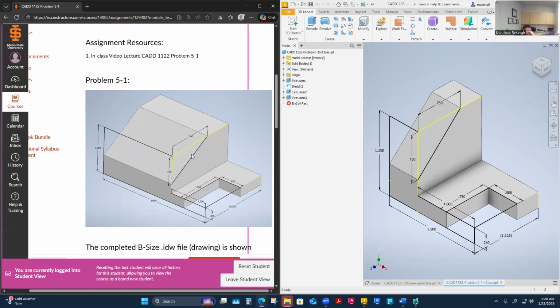7 core. So it looks like this bevel changed to 1.25 inch instead of being this standard 3/4 by 3/4. See that I've chosen to cut that with probably using projected geometry. Your sketch probably looks a little different than mine, or maybe it doesn't. Then I need to change the length to 3 inches, or the width, I should say. That's the width in the front view, 3 inches. And then a 2 inch deep extrusion instead of 1 1/8 inches. And then it looks like I have some modifications to that cutout sketch. So pretty much a lot of stuff changed on it.